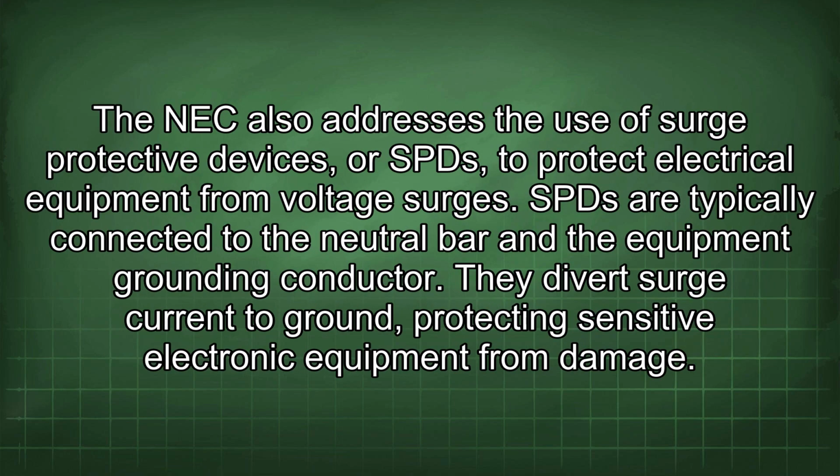The NEC also addresses the use of surge protective devices, or SPDs, to protect electrical equipment from voltage surges. SPDs are typically connected to the neutral bar and the equipment grounding conductor. They divert surge current to ground, protecting sensitive electronic equipment from damage.